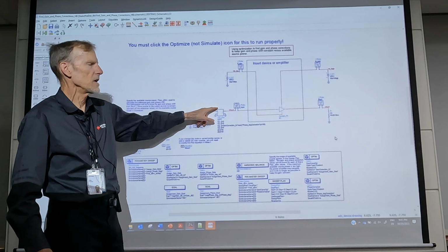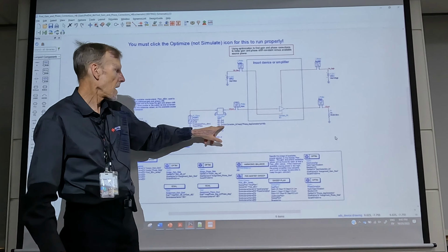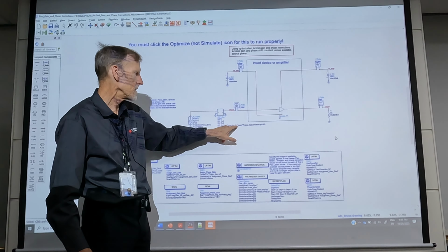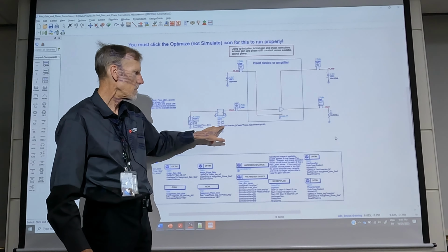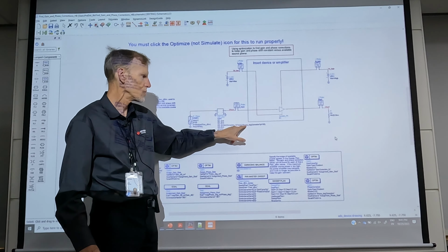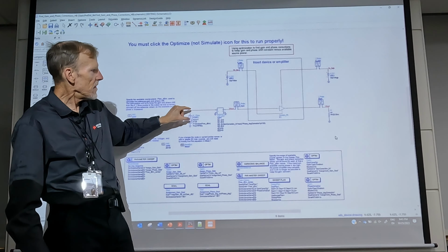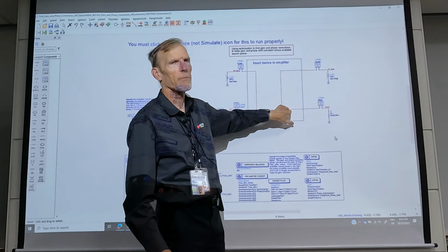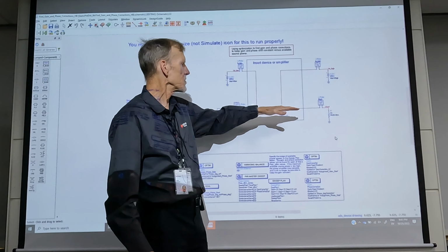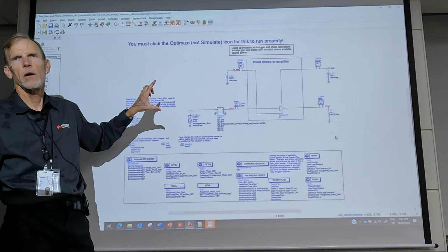It's a linear S2P, a two-port S parameter block, and I have to find a gain correction term and a phase correction term, such that the output gain and the phase shift through the amplifier remain constant as we increase the source power.